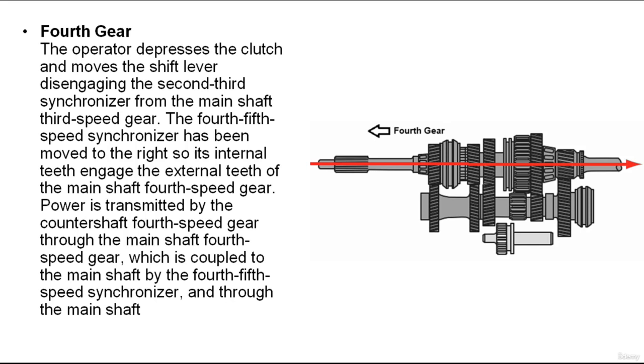This ratio results in maximum speed output and no torque multiplication. Fourth gear has no torque multiplication because it's used at cruising speeds to promote maximum fuel economy. The vehicle is normally downshifted to lower gears to take advantage of torque multiplication and acceleration when passing slower vehicles or climbing grades.